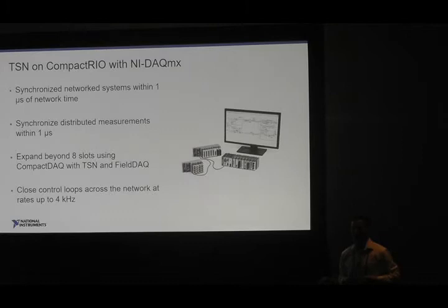And 1 microsecond is the broad timing that we use just to be safe, but in reality, you're going to see within the low hundreds of nanoseconds for that kind of jitter between measurement signals. So very well synchronized control all over standard Ethernet, so you don't have to develop a specific network or route an additional cable to do some hardware-based methods within the system.